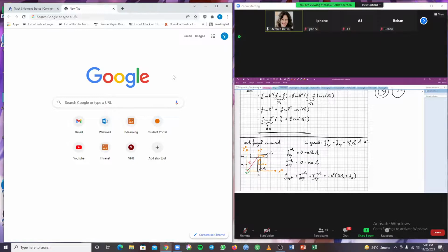You would start out with your main axis, then you could shift the main axis. For the centrifugal moment, you have to multiply the distance in X and Y direction, and then multiply this by the area itself. And then you sum your subsystems to obtain the global centrifugal moment.